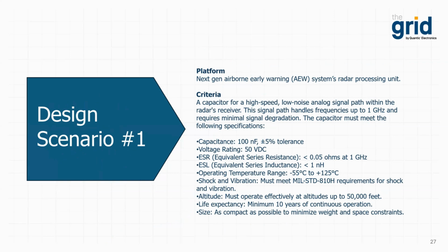The capacitor must meet the following specifications seen on the screen that include 100 nanofarads with a somewhat tight tolerance of plus or minus 5%, 50 volts, and so forth as seen on the screen.